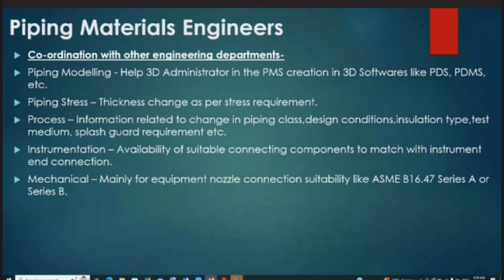And then piping stress, thickness change as per the stress requirement. So as I told you, the role of the piping stress engineer is to check the stresses developed in a pipe. Sometimes it is required to change the layout of the pipe to reduce the stresses, and sometimes we have to increase the thickness of the pipe. Then the stress engineer will say, okay, increase the thickness of this pipe or this component. Then we will increase the thickness of that component.